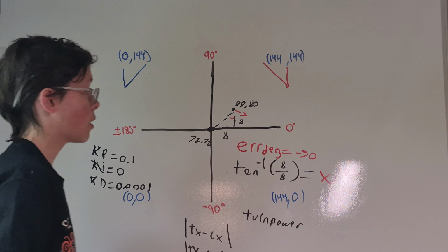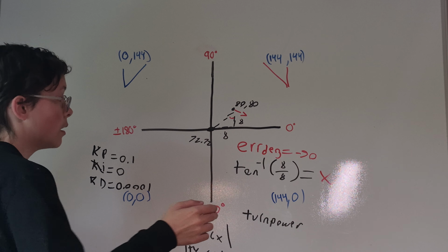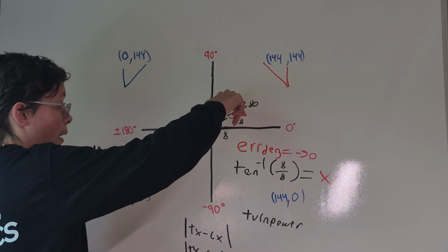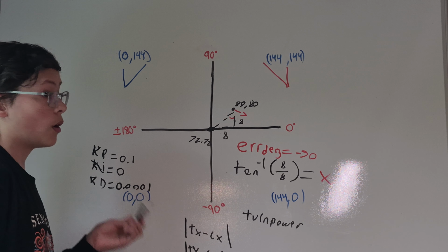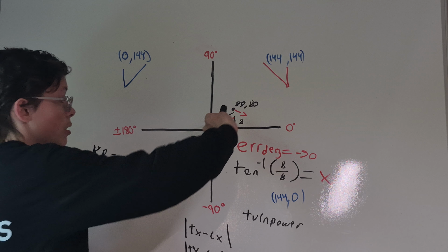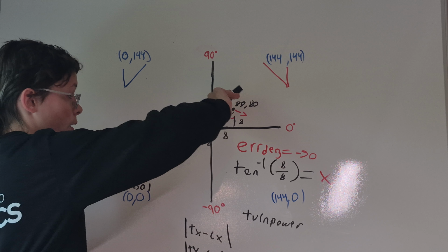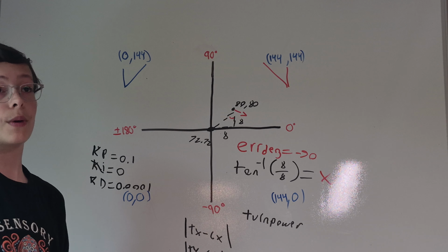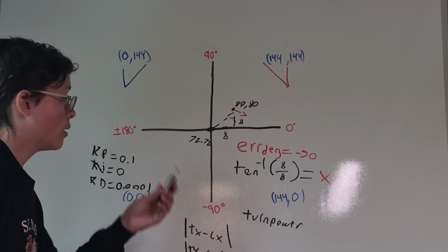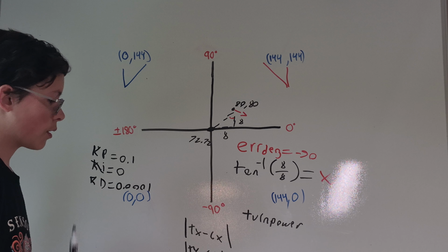This will be applied to our motors during the automated state to slowly give it a power and let it start turning. This equation is run over and over again until its position gets closer and closer to the target. When it eventually hits there, it will stop, but it will keep correcting when it's done. That is how that system works.